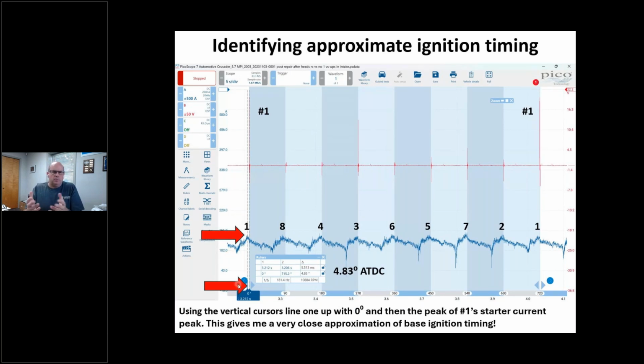Okay. I know what you're thinking. Hey, Chris, most engines fire at 10 degrees, 12 degrees before top dead center. I don't disagree with you, okay? But I can tell you on these marine engines and many, many automotive engines, gasoline, it's not uncommon to see spark timing just a shade retarded, especially during cranking sometimes. Sometimes they're advanced. It just depends on what the engineering wants.